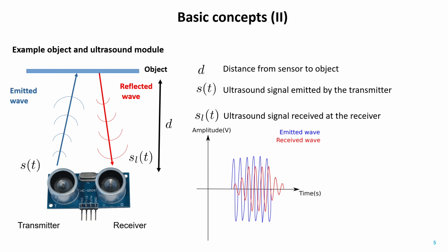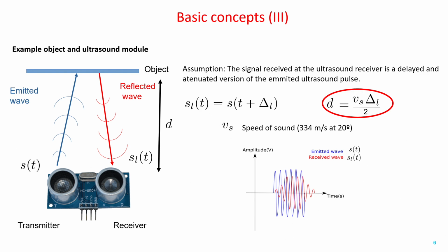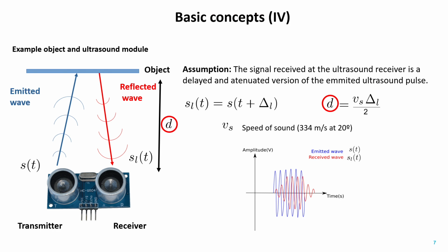In our context, the ultrasound module used, specifically the HC-SR04, emits an ultrasonic pulse that collides with the objects in the emission direction, and then receives its echo pulse, which is an attenuated and delayed version of the emitted pulse. The time delay between the emitted pulse and the received echo, combined with the known speed of sound, allows us to calculate the distance to the collided object. Finally, we will find the desired distance measurement by using the transmitted and received pulse train.